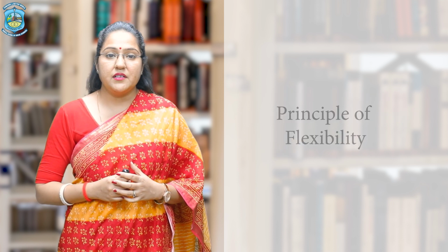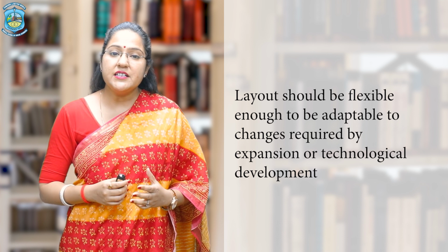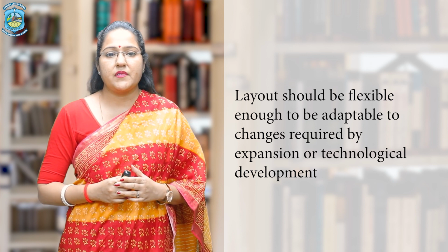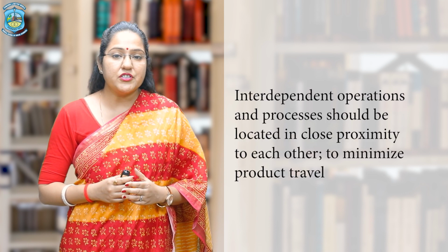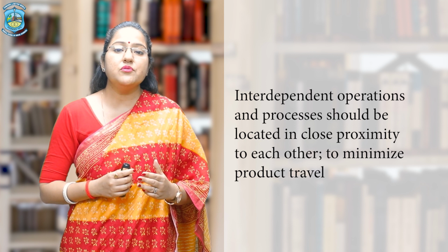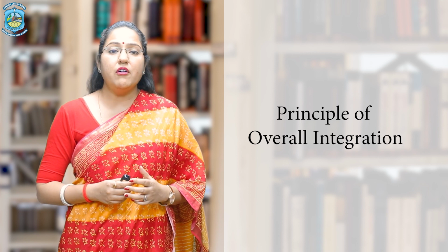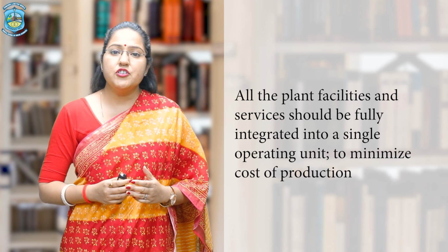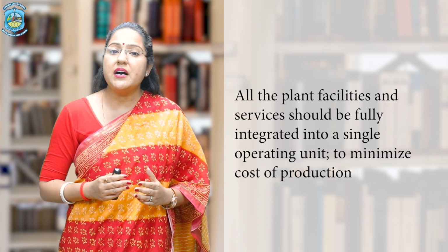Principle of flexibility. Layout should be flexible enough to be adaptable to changes required by expansion or technological development. Then, principle of interdependence. Interdependent operations and processes should be located in close proximity to each other to minimize product travel. Then, the principle of overall integration. All the plant facilities and services should be fully integrated into a single operating unit to minimize the cost of production.